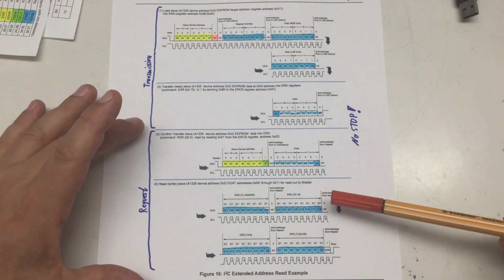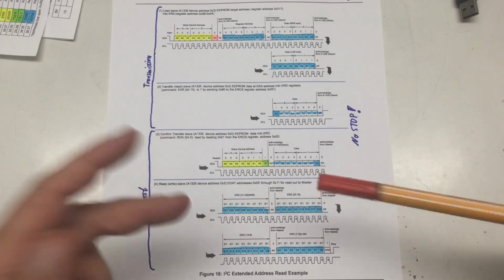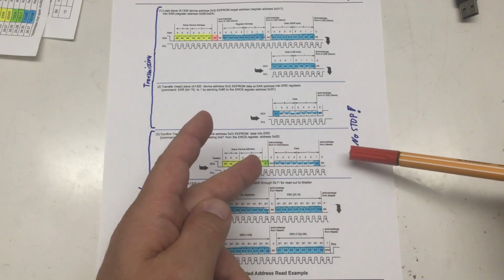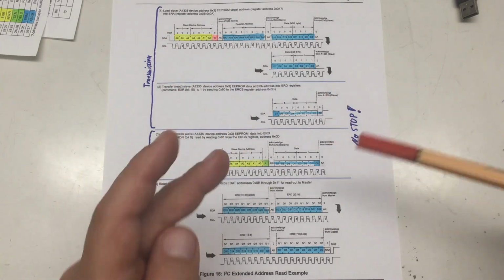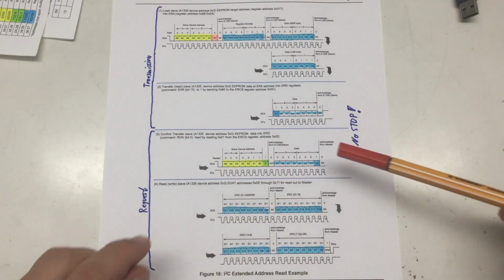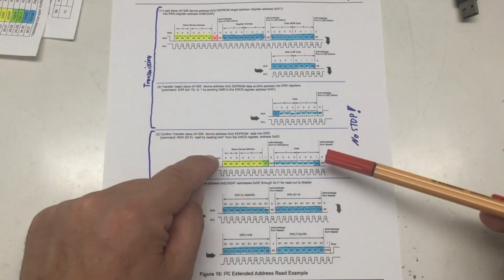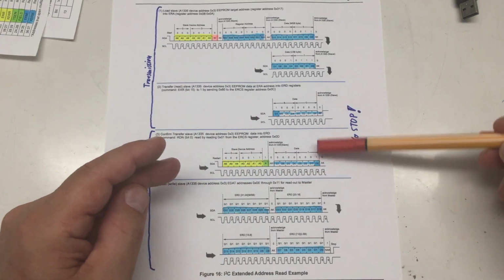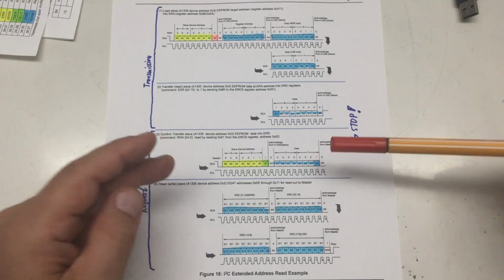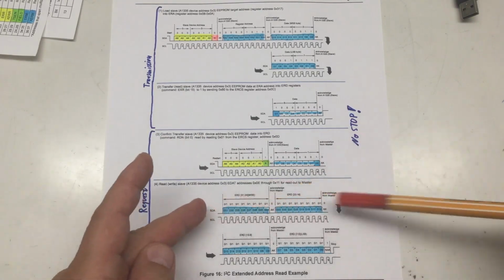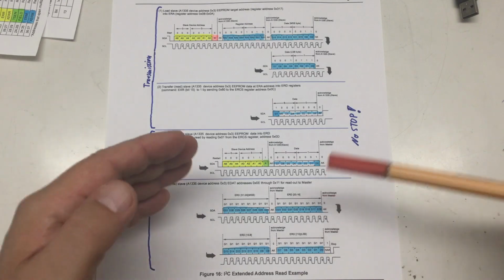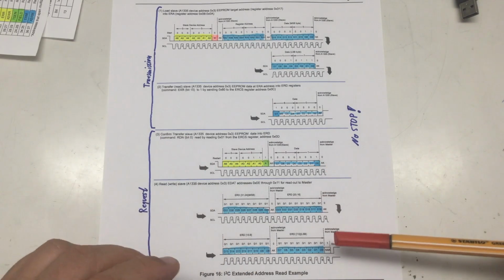Then we have in step 2 a request to the A1335 where we basically read out the second byte, the least significant byte, from the extended read control and status register, and hopefully the read done bit here, the last bit, is set, and then we read the 4 bytes, 32 bits, of the extended data.